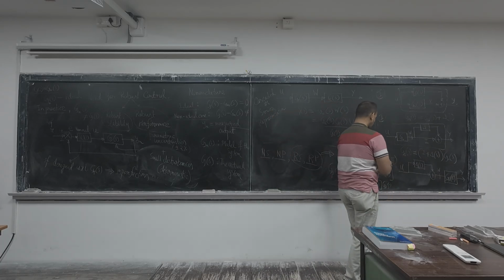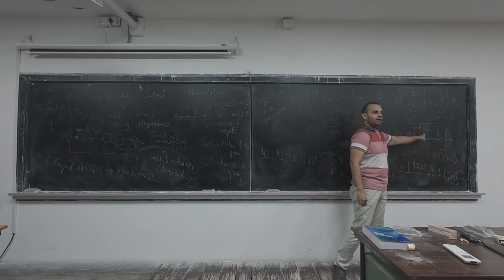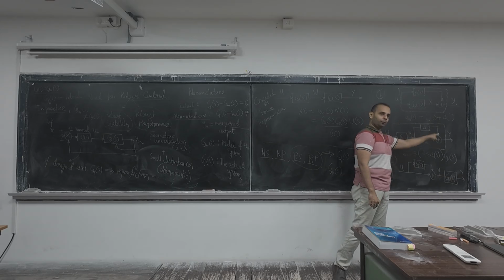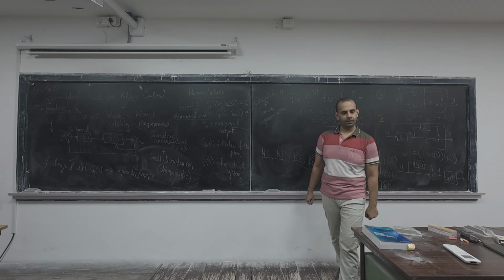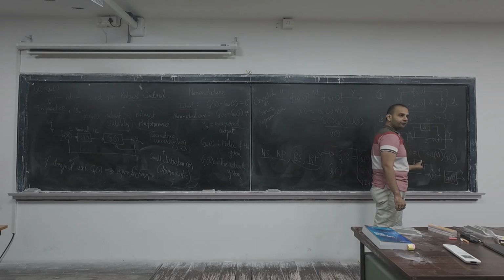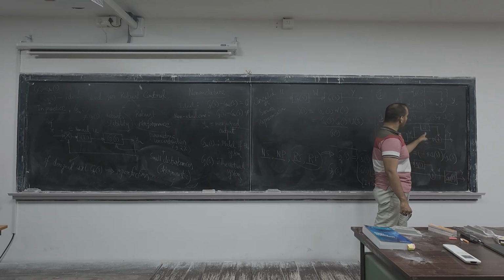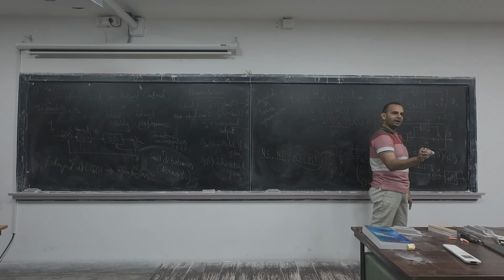Right? So this is my third representation. Here the uncertainty appears in the multiplicative format, but it is also appearing at the output side. The uncertainty is at the output side, right? So that's why it is called output multiplicative uncertainty. Once again, here it is in the multiplicative format, G0 into something, and on top of that, the uncertain block delta is closer to the output compared to the G0, right? That's why it is output multiplicative.